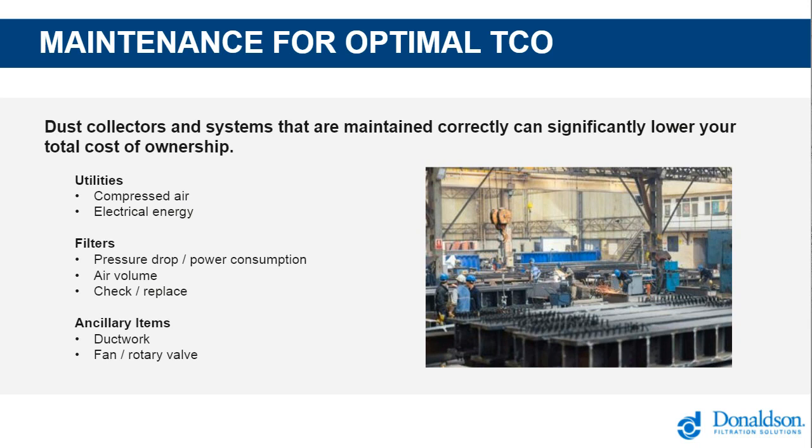But not only the compressed air in itself, it will reduce the wear and tear on the filters, the cages, the diaphragm valves, etc. And then electrical energy, we all know that's a high cost in relation to the high kilowatts that can be consumed. So think of possible uses of inverters, high efficiency motors, and then that's also linked to pressure drop. We were talking earlier about pressure drop and energy consumption, then draw that comparison between the two.